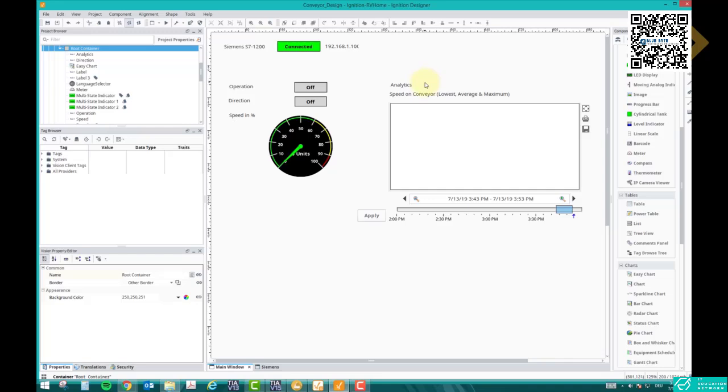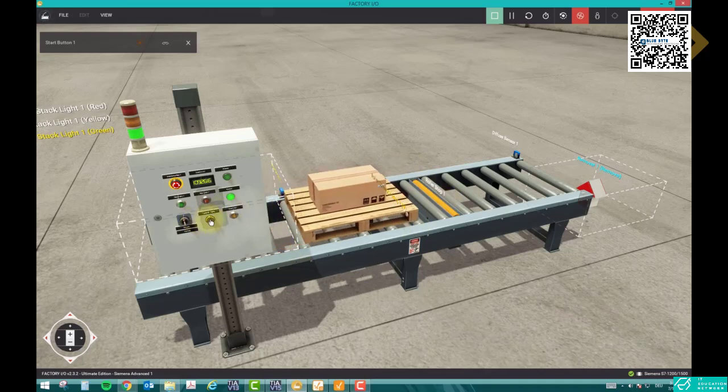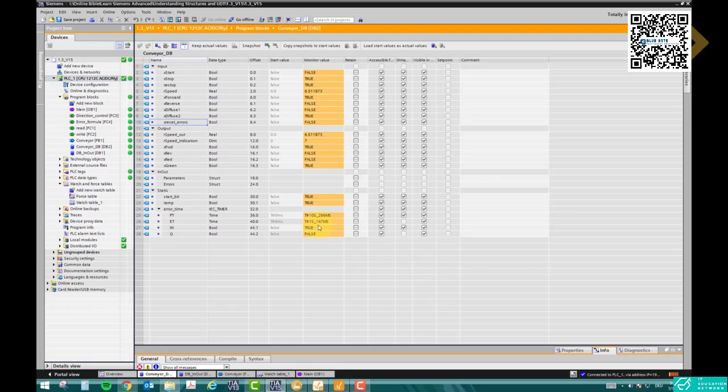Okay, and what else we can show? We can show about the time travel of the box, for example, for how much time the box was on the conveyor. Because if this is the fastest speed right now, if I reduce the speed, the box will be for more time on the conveyor. That we can relate depending upon the speed of the conveyor. Okay, and we have this parameter coming here. This is the time which is being recorded. Okay, so we will read this time and put it in the database, and then we will make some analytics.